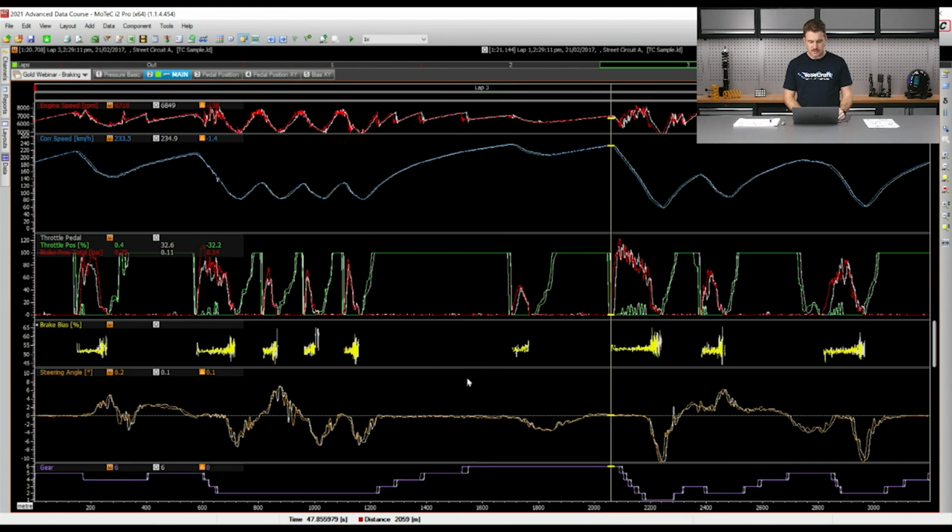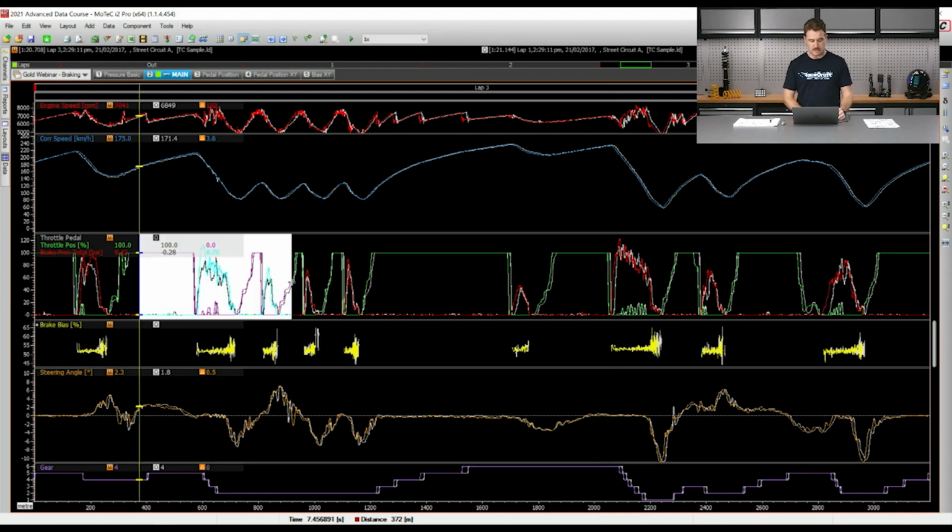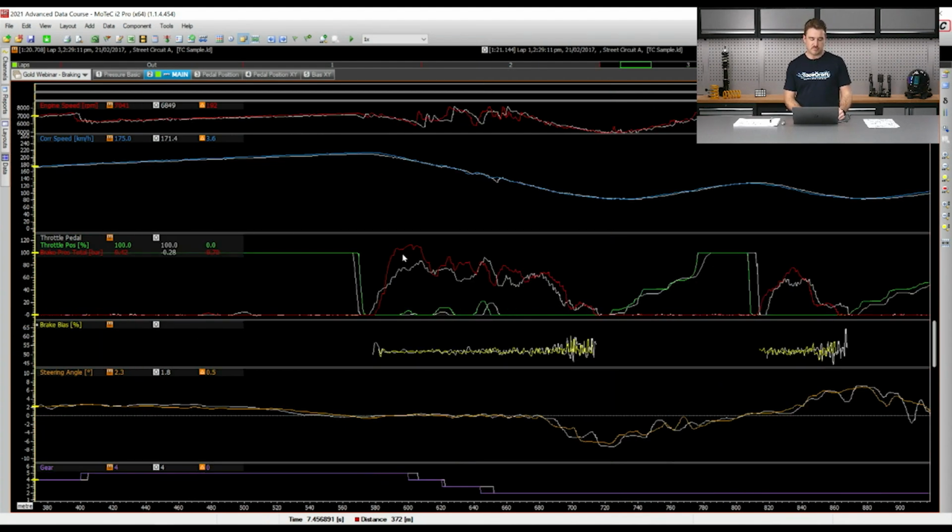The other really important thing, like we talked about, is looking at the brake pressure itself, the actual magnitude. So let's zoom into another part here. We've got a couple of different examples of the peak brake pressure. In this colored example, the driver is using much more peak brake pressure initially compared to the peak that they're getting in this first place. So let's put a delta between them. Let me just make it a bit clearer if I put it here. So we've got 112 bar at this point, and at this peak, which is much later in the stop, it is 86. So that's a pretty big difference in the brake pressure.